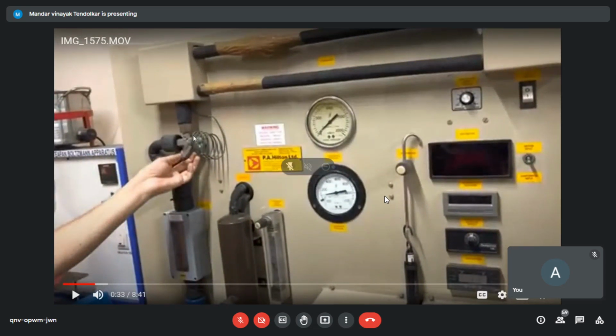This is your thermostatic expansion valve, correct? So that is my H3 is equal to H4. If you observe it from the pH chart, your pressure is reduced, condenser pressure to evaporator pressure, and the temperature also reduced. So that cooling part will be sensed over here, and then it will absorb the heat from the evaporator, which is those black tubes. Okay, so that is what is being shown.